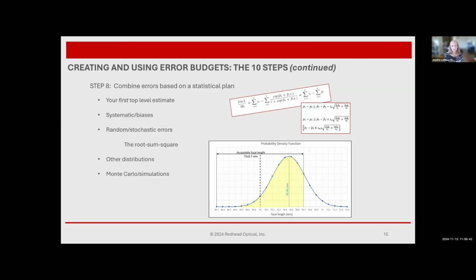However, let's go back to the 83% chance that I said. Given a set of tolerances and distributions, if you are truly using the correct distributions and the correct tolerances, this will tell you the chances of that optical system being in specification. So you may be only making 1 or 2. We could say that 83 out of 100 should be in spec, or you can say that for model number 1, there's an 83% chance that it will be in spec. So again, I do recommend using both methods.